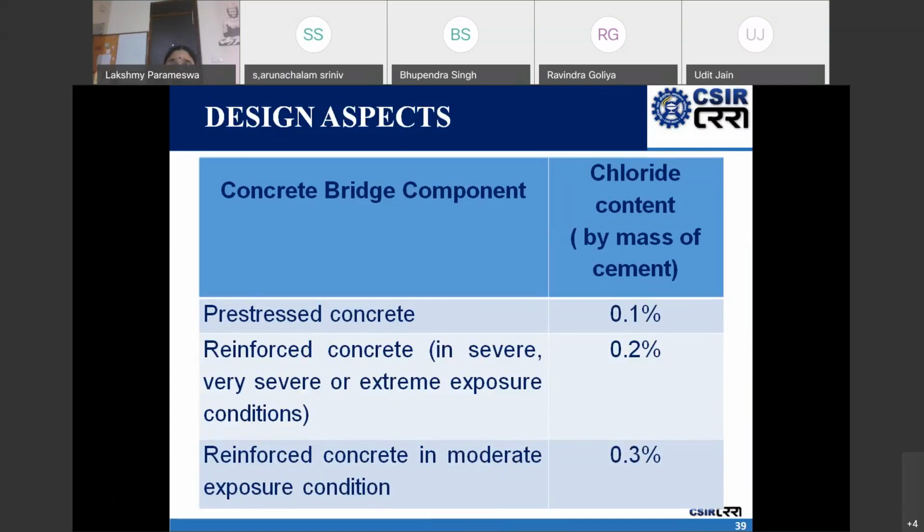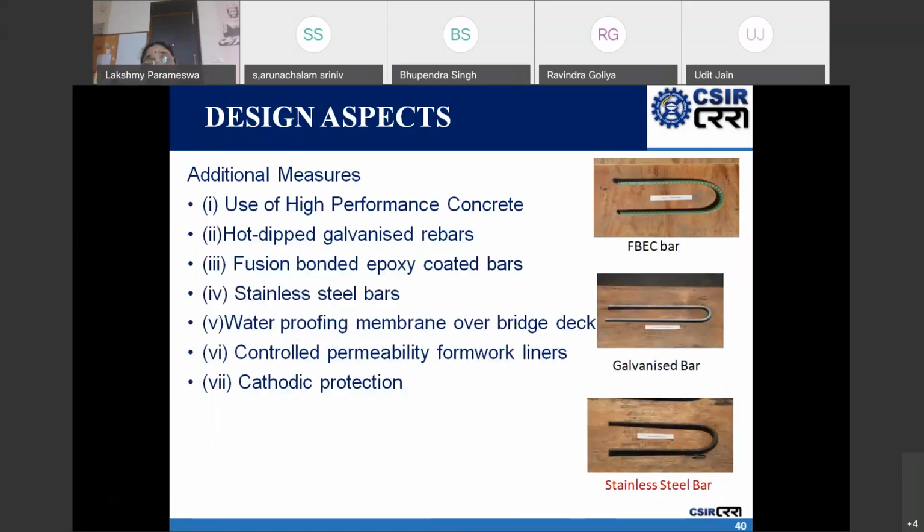So one will have to test the water we are using and aggregate we are using for all these chemicals, because chloride in concrete, if it is there during the construction, will enhance the rate of corrosion much faster, and carbonation induced corrosion is slightly a slow process, but the chloride induced corrosion is just like a cancer. So there are certain additional measures which have been prescribed apart from the normal concrete cover, reinforcement cover, water cement ratio and minimum grade.